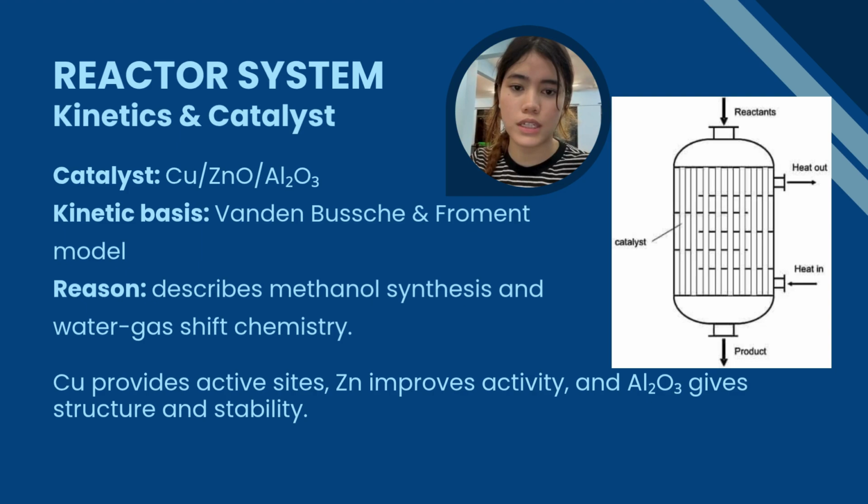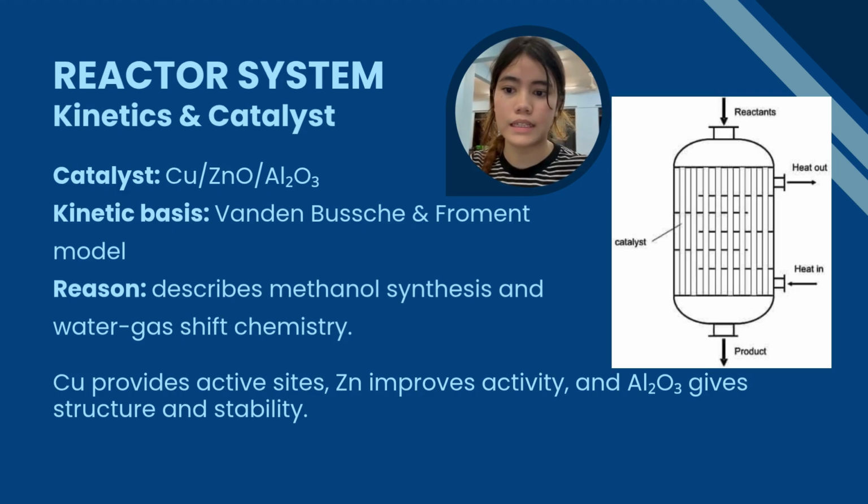For our literature kinetic basis, we preferred the Vanden Bussche and Froment model. The important point from the kinetics is that the reaction rate depends on temperature, reactant partial pressure, adsorption effects, and how close the reaction is to equilibrium. As methanol and water accumulate, the net forward methanol production rate gradually decreases. So based on these kinetic and thermodynamic considerations, we selected the following reactor conditions.